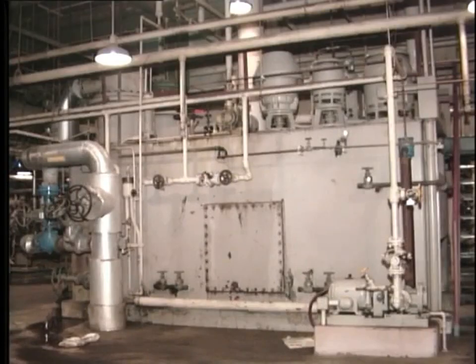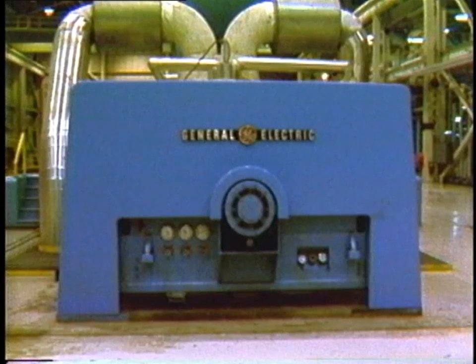We'll be looking in much more detail at the turbine control system in the next module in this series. For now, we're just looking at applications for hydraulic oil. In many turbines, the same grade of oil is used for both applications, so the hydraulic and lube oil systems are combined to utilize the same oil tank and the same pumps. The main oil pump is mounted in the front end pedestal and is driven directly from the turbine shaft.